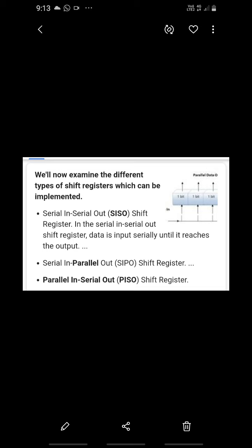When the 1 on the input is removed, the flip flop remains in the set state, thereby storing the 1 bit. The same procedure is applied to the storage of 0 bit.